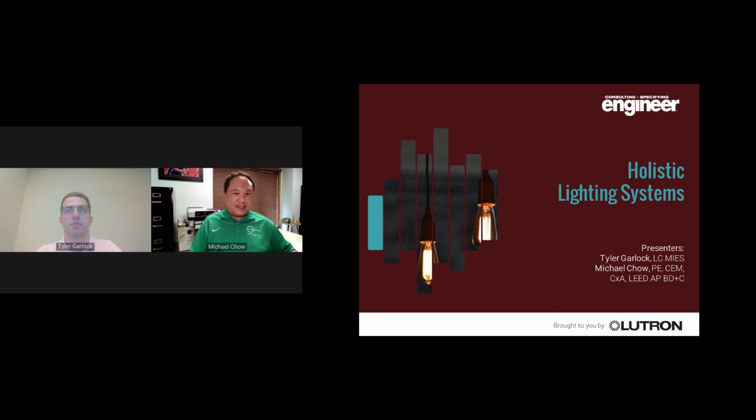And I think we talked about vacancy sensors too. ASHRAE 90.1 2010, which is LEED version 3, is based upon that. It doesn't require vacancy sensors, but that's something that you can do to help save energy. And in LEED, that could get you some extra optimized energy performance credits.